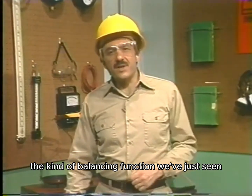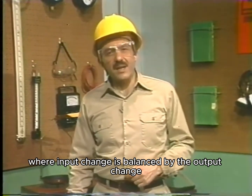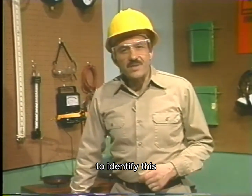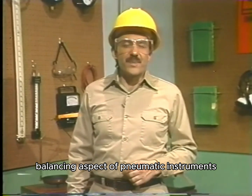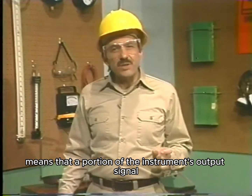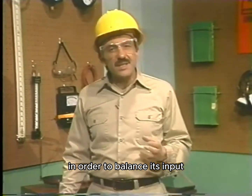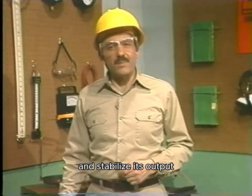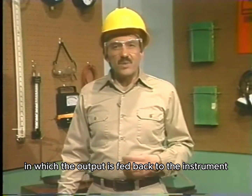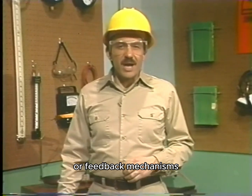The kind of balancing function we've just seen is common to many pneumatic instruments where input change is balanced by the output change. Now, there's another term that you'll be hearing to identify this balancing aspect of pneumatic instruments, and that's feedback. Feedback, in this sense, means that a portion of the instrument's output signal is returned to the instrument in order to balance its input and stabilize its output. As you work with pneumatic instruments, you'll come across a number of ways in which the output is fed back to the instrument. But that's enough about balancing or feedback mechanisms.